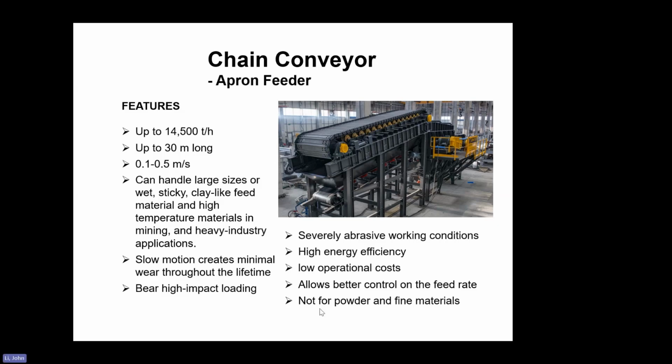But it is not suitable for powder and fine materials because this pan is overlapped. They have a gap between the pans. So if you have powder, fine particles, it will leak underneath.